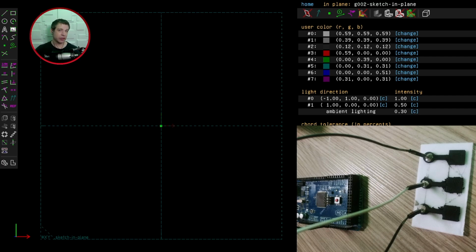The pins on the Arduino to which the keys are attached are floating, and by touching each key you're grounding those pins, which the computer will then detect and then generate a sound like you would if you pressed a key on the piano. And it sounds something like this.